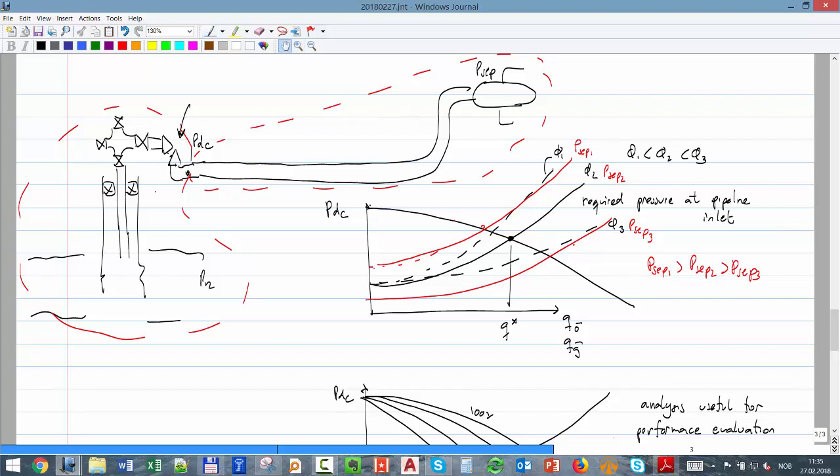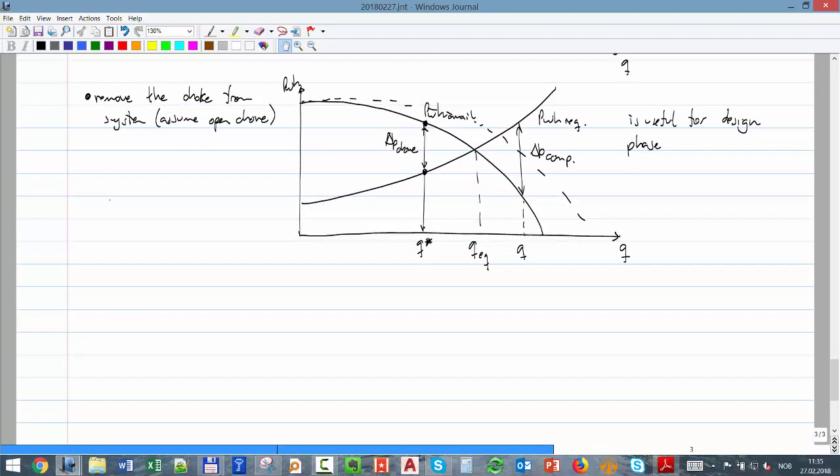We are saying like if we are going to install a compressor or we are going to install a choke here, right? But if the pump usually is installed here, the ESP, so I have to move and I have to calculate the required curve to this point and the available curve on that point. And there I can say exactly that's the delta P my ESP needs. Okay? So I have to move, remember, and that has to be for this type of analysis.